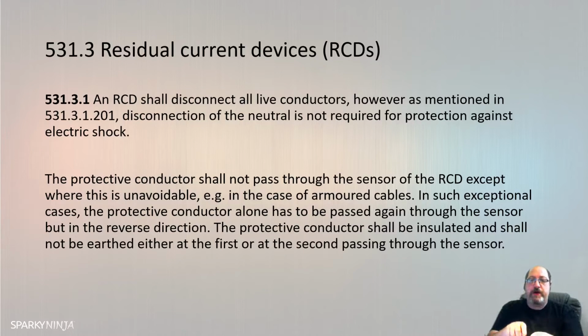So if we had that scenario, let's say that line takes 5 amp down, but neutral has just 3 amp going back. That means 2 amp is lost, and that 2 amp has gone to earth. But that earth is also going through that RCD, so that 2 amp on earth is also going that way. So you have 5 amp going down, then you have a 3 and a 2 going up, which is 5 up. So 5 down, 5 up, it doesn't detect the imbalance.